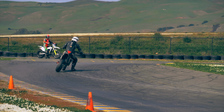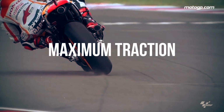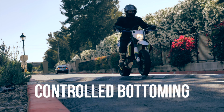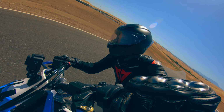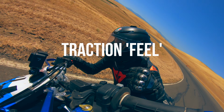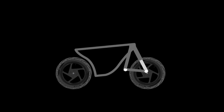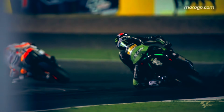Let's think back to the goals with an ultimate suspension system. We want maximum traction, traction feel, controlled pitch, minimal harshness, controlled bottoming, and consistency. While Earl's forks are theoretically good at almost everything, they lack traction feel. First of all, having the front end rise when braking is counterintuitive, so it is something that a rider would have to spend a long time getting used to. Secondly, with added pivot points comes added play in the system. This removes feel of the front wheel traction.